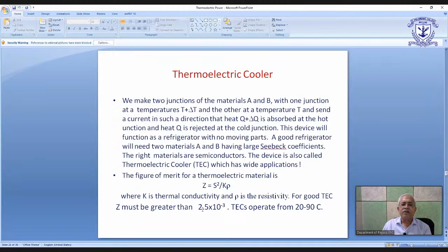A laser diode efficiency drops when the temperature of the device goes up, which is not very desirable. So wherever we use a laser diode, and if we want a stable light output from the laser diode, it has to be mounted on a thermoelectric cooler, which will keep a check on the temperature of the device and keep cooling it.